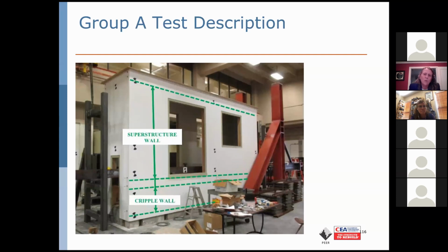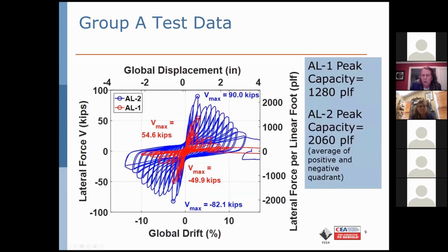This is our three-dimensional large component structure that we did for the cripple wall testing with and without retrofit that you see right here. It has the stucco run down the face of the foundation. Tara has already shown you marvelous graphs of with and without retrofit superimposed, and this is following exactly the same pattern. We were interested over the entire range of drift ratios, which was really the way we imposed the loading protocol that Farzin had come up with. They were all of interest.